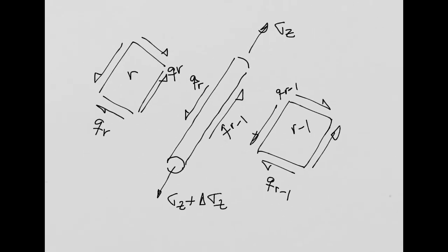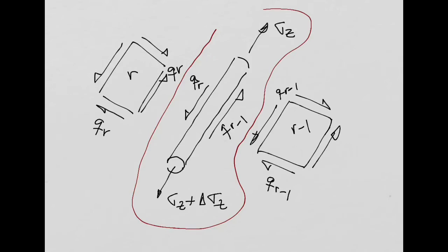Did you understand what I did here? So a quick summary again. This shear stress is the shear that the boom is doing on the skin. So the skin will react on the boom by applying the same shear stress, same value or same intensity, but in the opposite direction. Action-reaction, right? Newton's third law. And you do the same for the other skin on the left side. And then you get your boom, this one, with all the forces we have there.